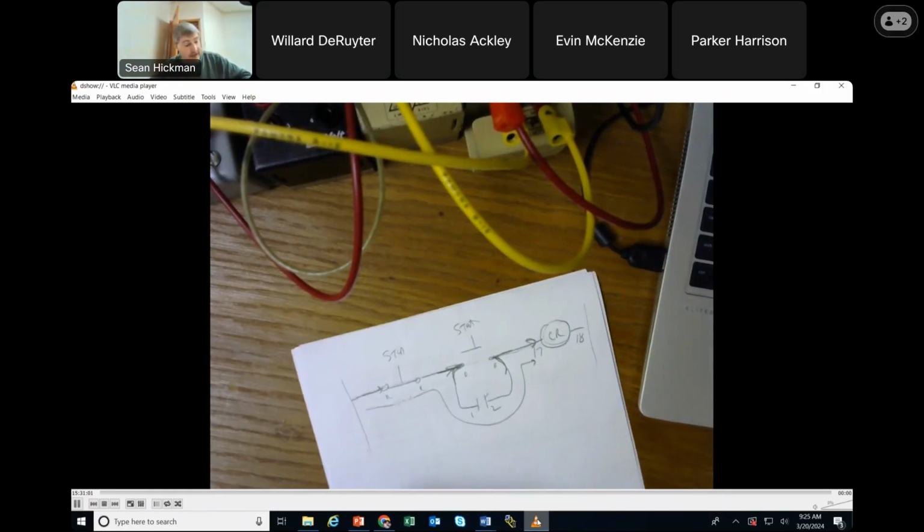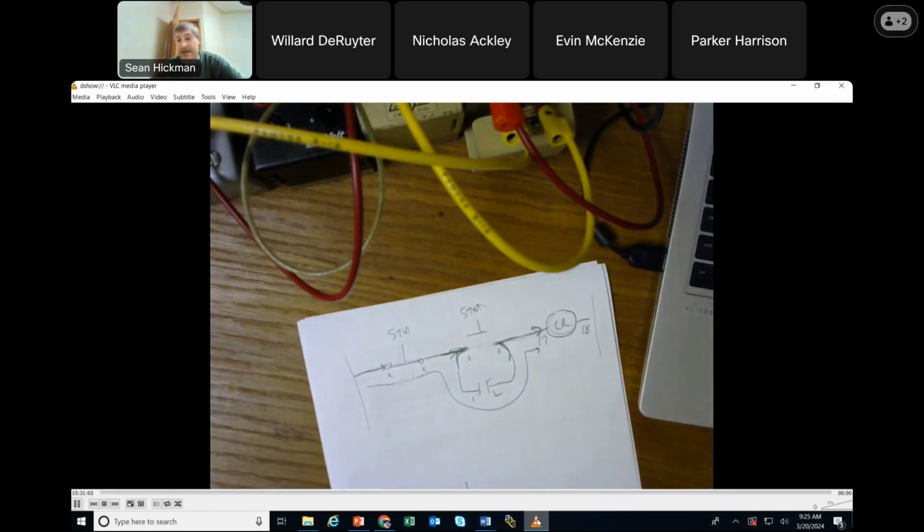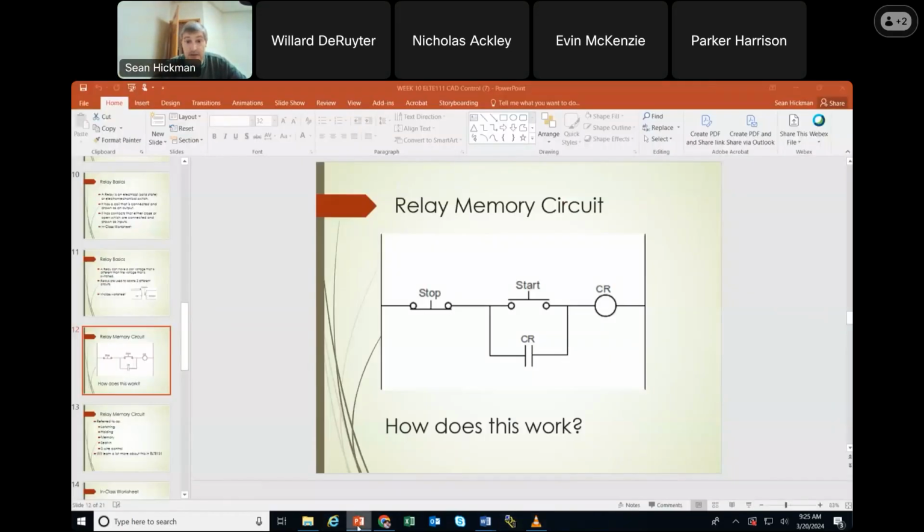So on a scale of 1 to 10, does that memory circuit kind of make sense to you, that the relay kind of turns itself on, or keeps itself on, let's say? Called a memory circuit, okay? And that's what you'll be hooking up, all right? So how does that work?